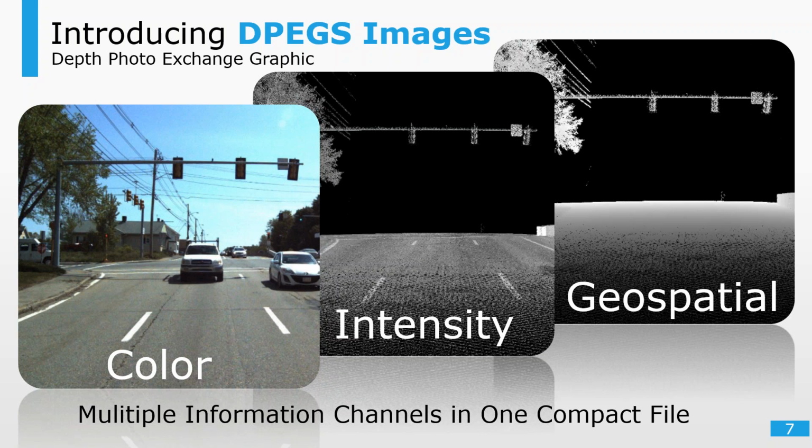So now, say this JPEG image is one that was taken from a mobile LiDAR system. TopoDOT automatically extracted the intensity that goes along with that, and also the geospatial information, which is the point cloud. Each of these is a range point that corresponds to a pixel. If you imagine you overlaid them over each other, when you click on the JPEG, you get the range information in the back, and you are able to extract measurements, locations, things like that. This 4 meg file only goes up to about 7 meg with this information,